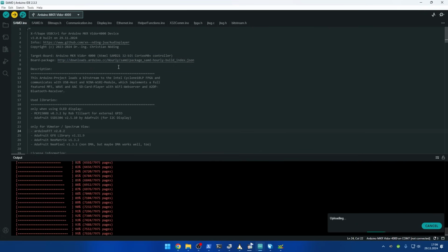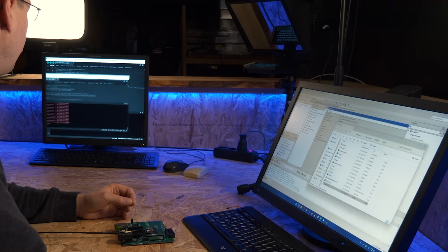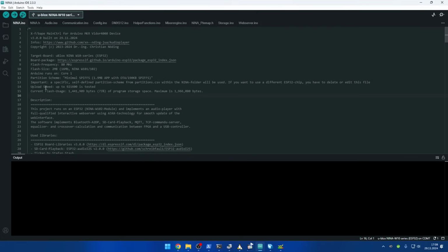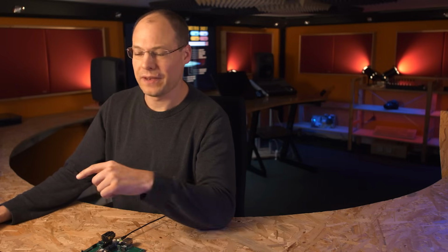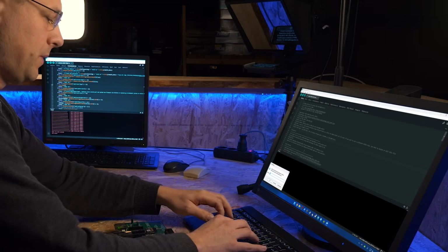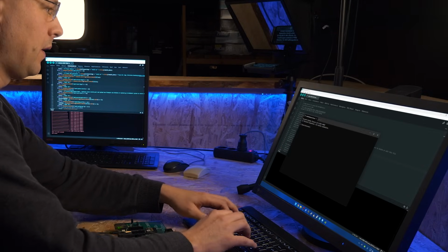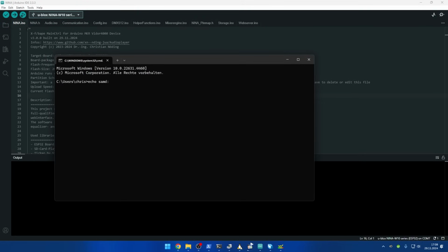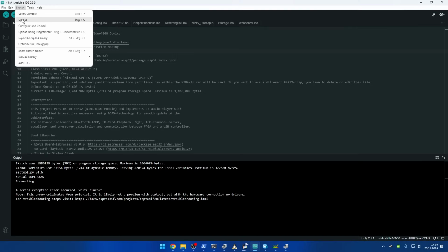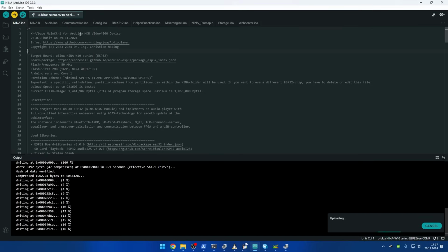So far so good. Now we have to upload the code to the ESP32. And to upload our code, we have to set the SAMD21 to firmware update mode so that it passes all serial communication to the ESP32. So I'm using the command here, echo SAMD update Nina to COM7. Yes, the LED is now blinking a bit faster, and upload the Nina firmware.